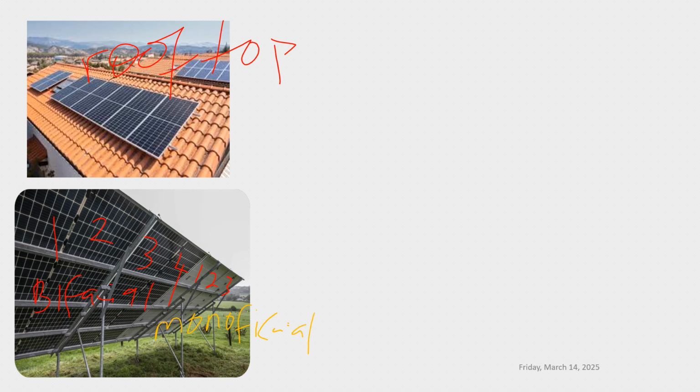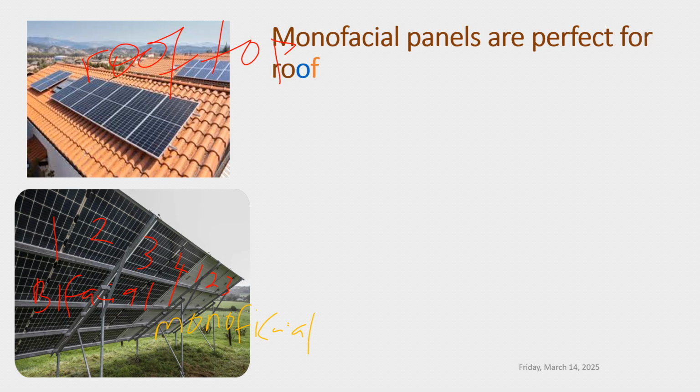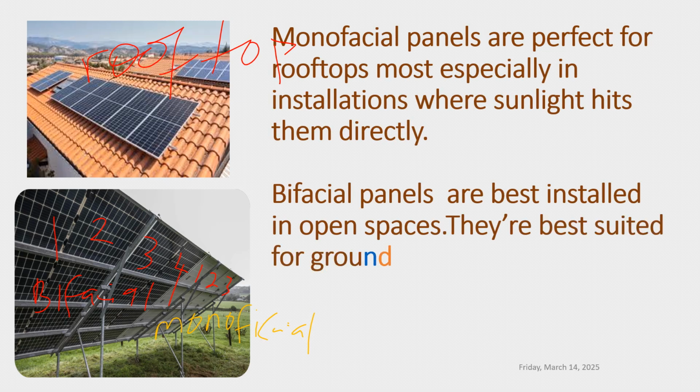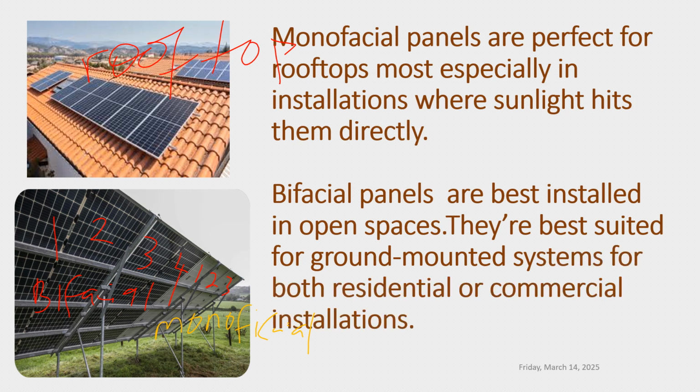So it's not that you can't use them for carports or for things other than the rooftop. You can use both, but bifacial is more efficient on a carport or a steel structure compared to using them on the rooftop. That's what I just want to tell us. Monofacial panels are perfect for rooftops, most especially in installations where sunlight hits them directly. And let me tell you, install your solar panels on the rooftop, most especially on the south side.